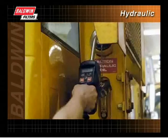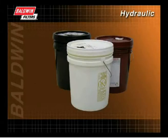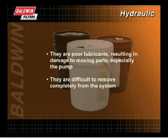Some manufacturers recommend flushing hydraulic systems with regular hydraulic fluid, while others recommend the use of solvents or cleaners. When flushing the hydraulic system, follow the manufacturer's recommendations. Some solvents and cleaners on the market today are not recommended for use in flushing hydraulic systems because they are poor lubricants, resulting in damage to moving parts, especially the pump, and they are difficult to remove completely from the system. Just a trace of some of the commercial chlorinated solvents may be enough to break down the oxidation resistance of even the best hydraulic fluids.